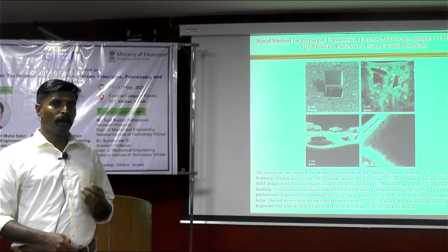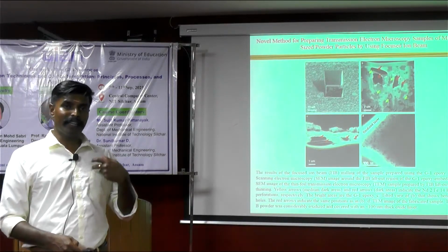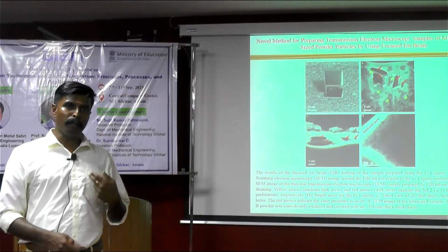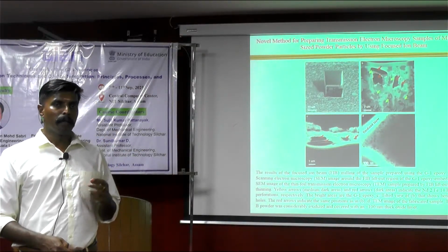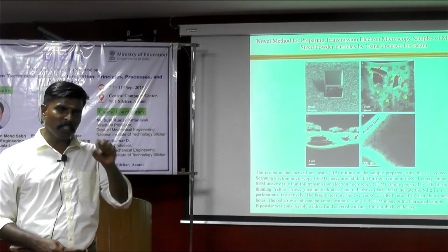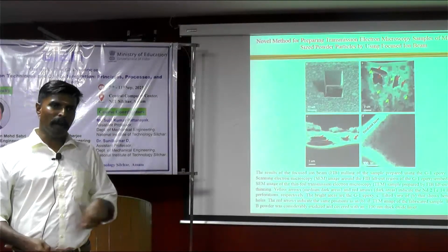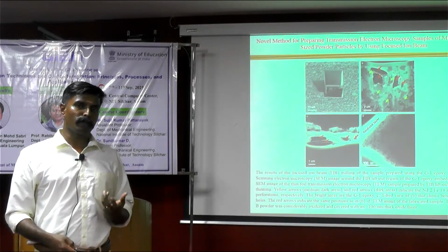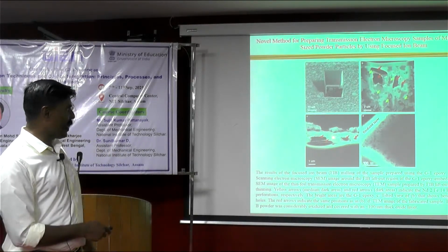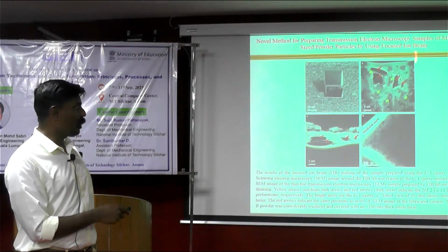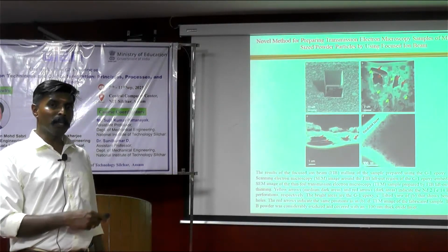The challenge behind TEM is to fabricate the sample for that microscopy technique, because it should be a thin film; the electron has to be transmitted through. Only then, with that pattern, can we identify the type or size of the precipitates. For that, micro machining techniques like FIB can be an alternative technique.